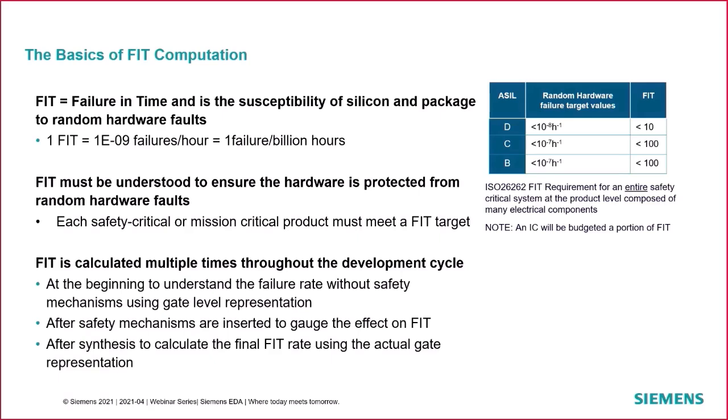For example, if there are 100K cars made using one design of a chip, they have to run for a minimum of 1 million hours altogether, to see that one FIT in 1 billion hours. So it's a vehicle level requirement as opposed to a chip level requirement.